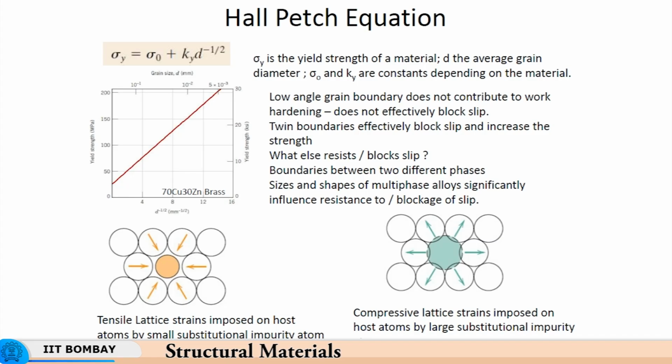So, you have to have dislocation movement, you need strain to be imposed on the material, that is a plastic strain, permanent deformation. But then to cause that deformation, you need an increasing amount of stress because you have dislocation movement being impeded by various factors, namely the dislocations which are already present, the interstitials which are present, and the pile up at the grain boundaries. So closer are the grain boundaries, greater is the work hardening rate.